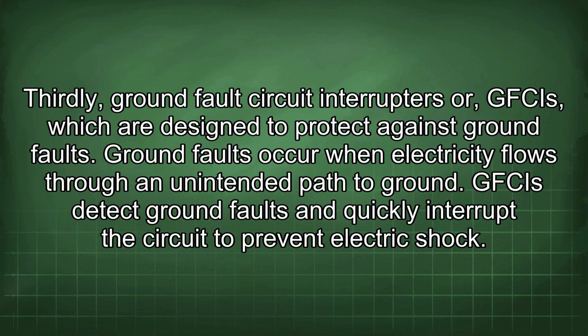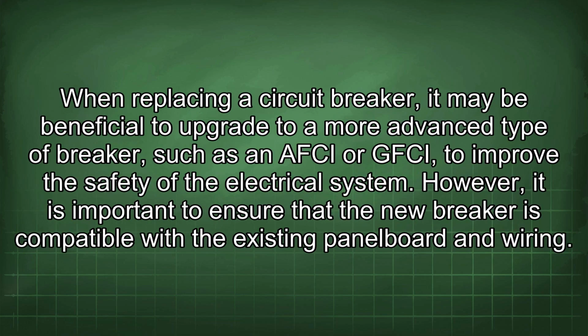Thirdly, ground fault circuit interrupters, or GFCIs, which are designed to protect against ground faults. Ground faults occur when electricity flows through an unintended path to ground. GFCIs detect ground faults and quickly interrupt the circuit to prevent electric shock. When replacing a circuit breaker, it may be beneficial to upgrade to a more advanced type of breaker, such as an AFCI or GFCI, to improve the safety of the electrical system. However, it is important to ensure that the new breaker is compatible with the existing panel board and wiring.